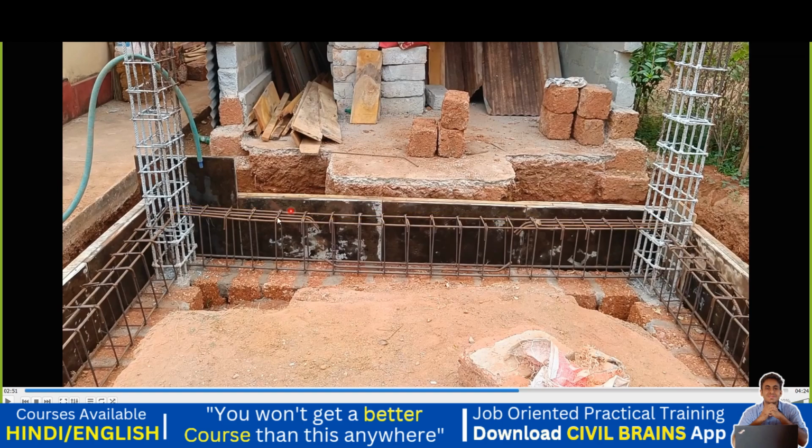Good. Now you check the column. See, I have a column here, I have a column here. For this particular beam, this column is the end column because beyond this we don't have any beam running. So this is my end condition, end support. Similarly this column is also an end condition because I don't have a beam running in this direction. We have a beam there, but that is not to be considered. You have to take the horizontal one. It depends on where exactly your beam is.